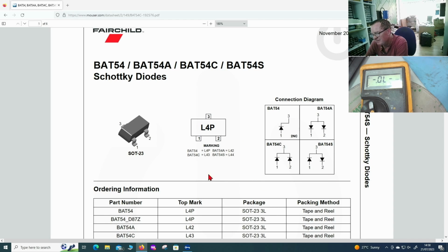In circuit, usually, but depends on the board, if they put the silkscreen markings, this will be called D followed by some number, D10, D21, whatever, rather than Q10, Q21, Q being a transistor, either bipolar or MOSFET. So watch out for those guys. They will confuse you in circuits and you think you got faults you haven't. And even when you take the thing out, you'll still think it's faulty, possibly, or you will not realize it's a diode matrix. Okay, just thought I'd mention that. Now we've talked about some of the things that can fool you with this. Let's have a look at in-circuit testing and look at the other things that can fool you with this.